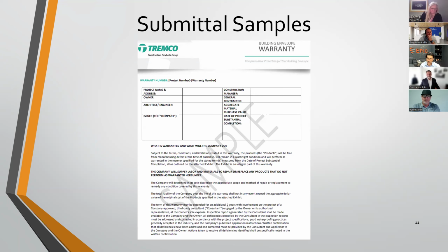And a 40-foot royal palm is obviously terribly massive, really heavy, and you have waterproofing in that planter that is going bad one way or another. If you have just a material warranty, you will be on the hook for removing that palm tree, removing the dirt, exposing that waterproofing. And once that waterproofing is exposed and cleaned, and you can then prove that it failed due to the mixing of the material by the manufacturer, okay, cool. You got a warranty item right there.